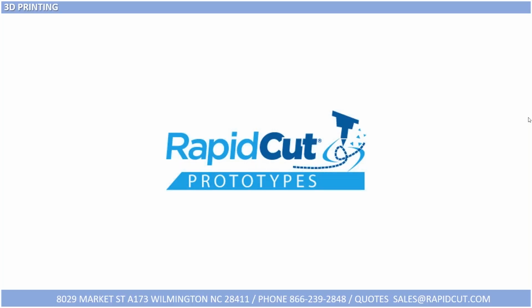Yes, fixtures. Got a good question here on fixtures. So yes, a lot of folks are using FDM and SLS primarily to create fixtures. DMLS could be used, but it's just not cost competitive. In a lot of cases, I wouldn't necessarily use it for a welding fixture, but if you're doing assembly fixtures, especially large ones, where aluminum is going to be a hindrance due to the weight, then an FDM or SLS fixture is an excellent solution for those types of applications.